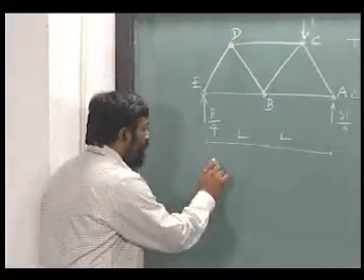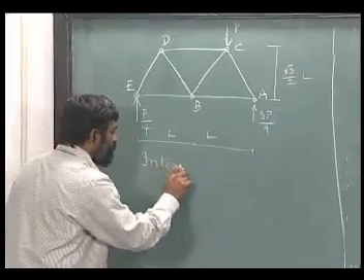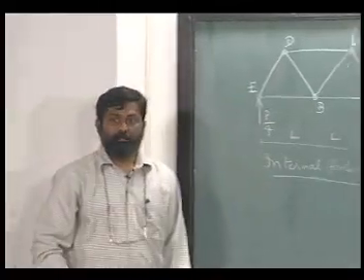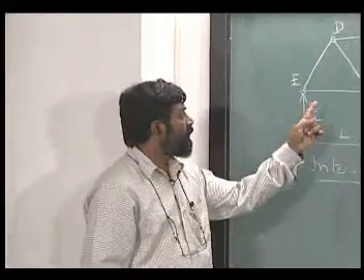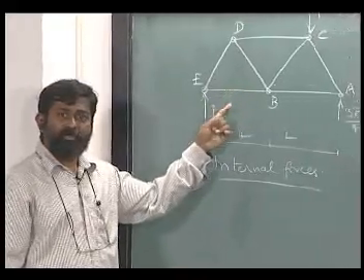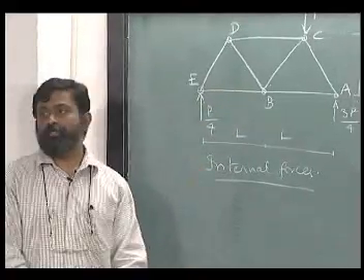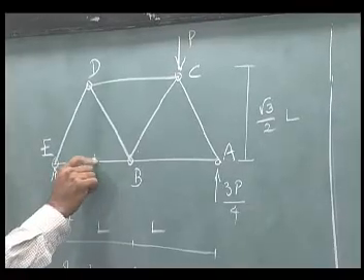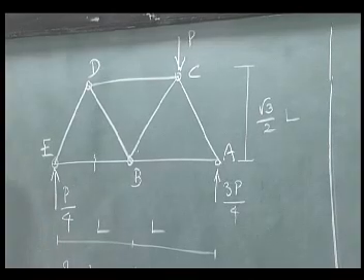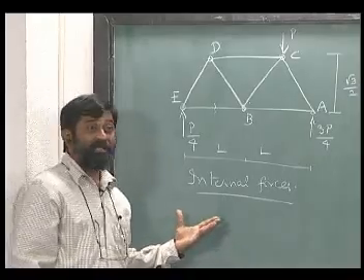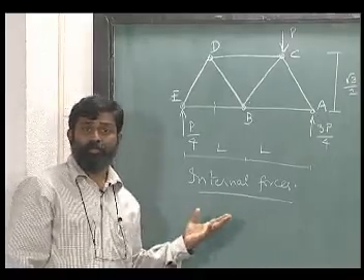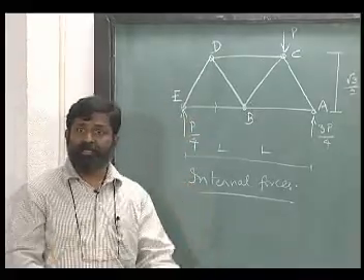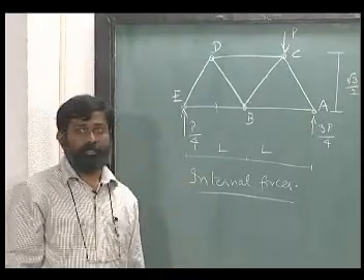As a first step to finding out internal forces, we know very well that we have to cut any one of those members for which we want to find out the internal forces. Supposing I want to find out the internal force in BE, I need to cut that particular member. Okay. So let us cut and see if we can find out how to solve for internal forces.